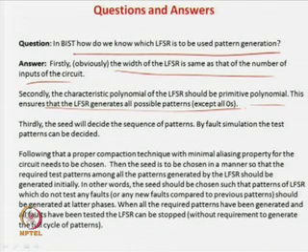So, the other way you can find out which are the most important patterns required to be generated. Accordingly, you can set the primitive polynomial. The characteristic polynomial may not be primitive if you are targeting only a few of the vectors. But for exhaustive patterns you can use the primitive polynomial. If you are using a primitive polynomial, all patterns will be generated, but if you can solve your testing with good coverage and non-aliasing with a few initial patterns, then you can also go for a non-primitive polynomial.